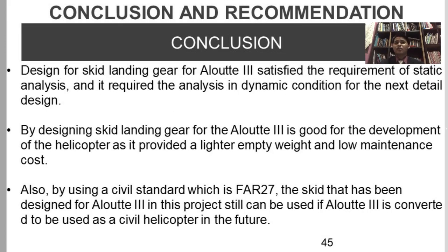Also, the design of the skid landing gear for the ALERT 3 satisfies the requirement of static analysis, and it requires analysis in dynamic condition for the next detailed design. Designing the skid landing gear for the ALERT 3 is good for the development of the helicopter, as it provides a lighter empty weight and lower maintenance cost. Also, by using the civil standard, which is FAR 27, the skid designed for the ALERT 3 in this project can still be used if it's converted for a civil helicopter.